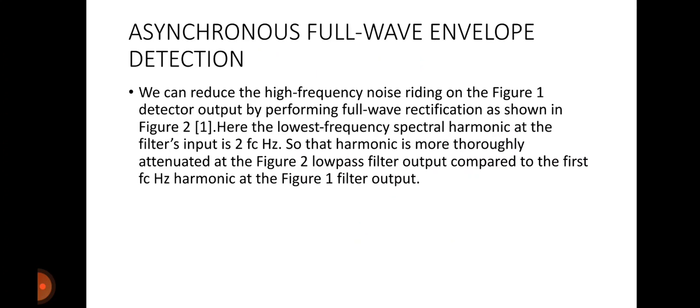Asynchronous full wave envelope detection. We can reduce the high frequency noise riding on the figure 1 detector output by performing full wave rectification as shown. In figure 1 we have done half wave rectification. By using full wave rectification we can reduce the high frequency noise.